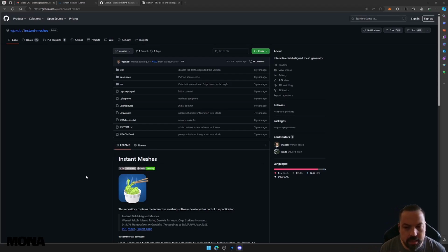So the remesh in other situations, in ZBrush, in Blender even, it actually has some pretty good automated remesh and decimation tools. But a really good one that pays attention to the lines of the asset rather than the polygons of the asset might even clean up your asset better than you've done it, possibly.